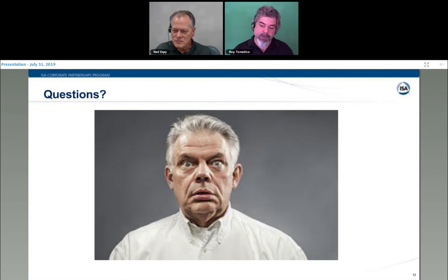That kind of feeds into the next comment by Julio. Julio mentions our corporate procedures mandate simulating the process variable, so pumping up a differential pressure cell physically to at least a 3-point calibration. That way you're exercising the transmitter. I fed this transmitter the equivalent resistance for an RTD temperature, so it's essentially exercising the transmitter as well.